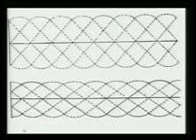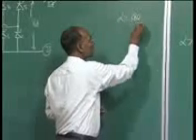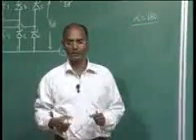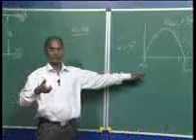Here let us draw what will be the output voltage in the case of inversion, where alpha, let's suppose, is 150 degrees. In the previous case, alpha was 180, which was just equivalent to a rectifier circuit. The voltage magnitude will be the same as when alpha was 0, only the polarity is different.